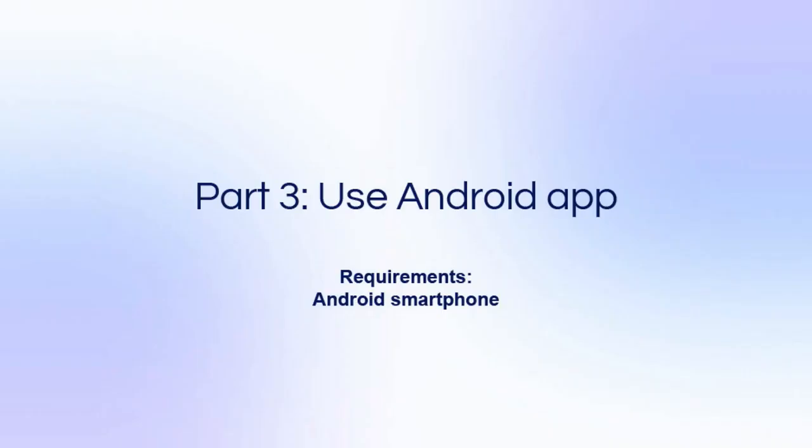In the previous section, we looked at the metadata on the ThingStack console. Specifically, the RSSI and SNR values gave us a good idea of how well our device is heard by the gateway. Looking at the metadata on the console is tricky, especially when you are walking around doing range testing. To make it easier, there is the Dtmapp mobile phone app.